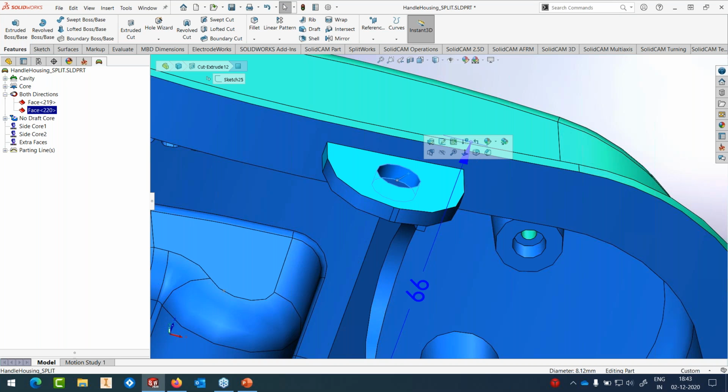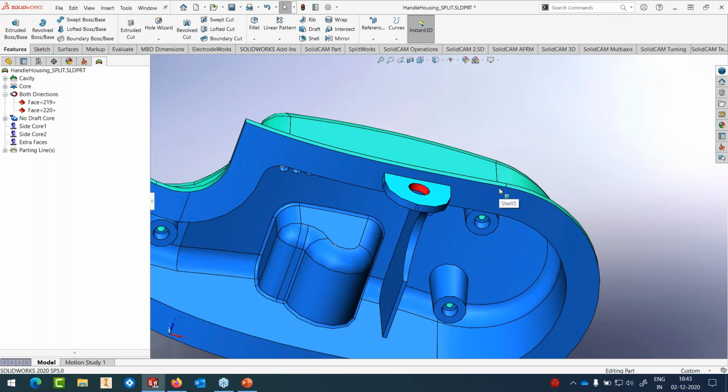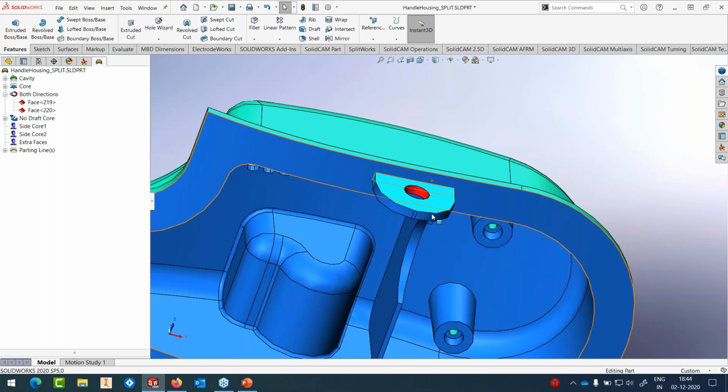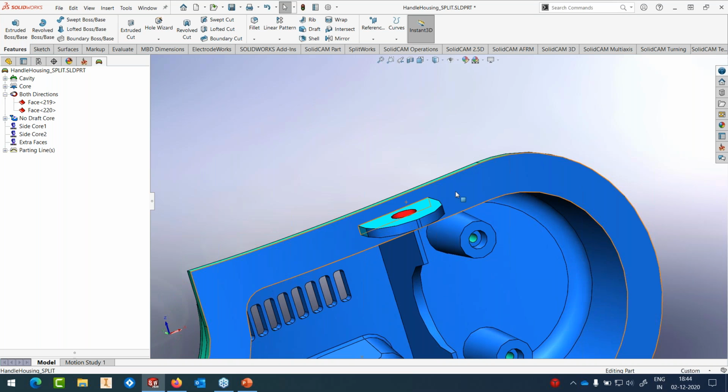It means that I need a 3+2 machine to accurately drill the hole and then do some kind of boring to make it pretty accurate. This is going to add to the cost of my machining. Not only cost, it will also add to the complexity of the whole design itself. Instead of that, I would like to make a small change, and that change will ensure that this particular part can just be done on a simple 3-axis machine with a little bit of EDM work, which probably will work out cheaper than taking this onto a 5-axis machine.